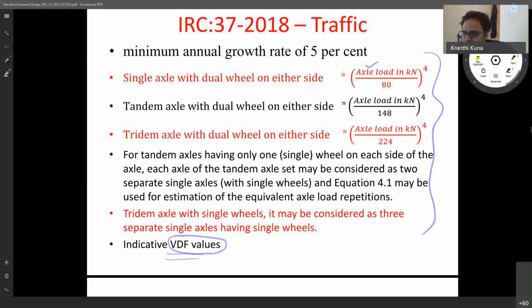So for the same pavement, adopting 90% and 80% gives different results. Rather than giving different equations for low volume roads and high volume roads, we have provided the same equation. You can think of less important roads and more important roads. The equation is the same, but the reliability factor will change, so that less important roads get lesser thickness for the same traffic.